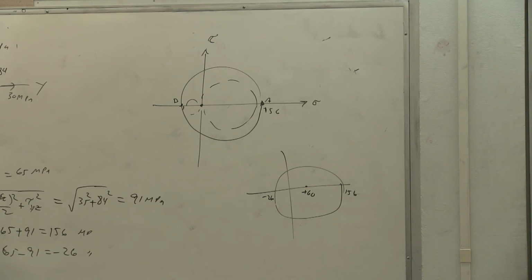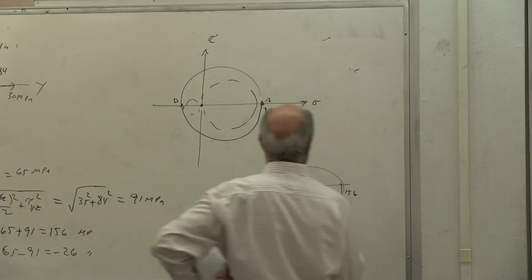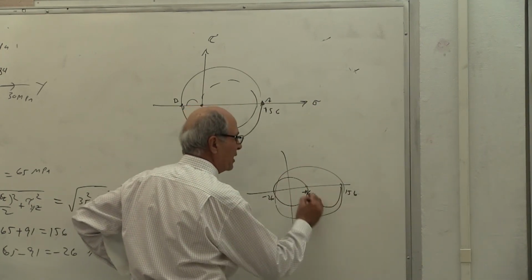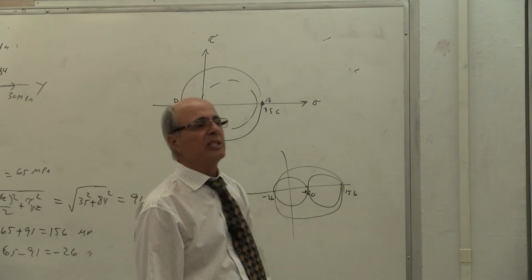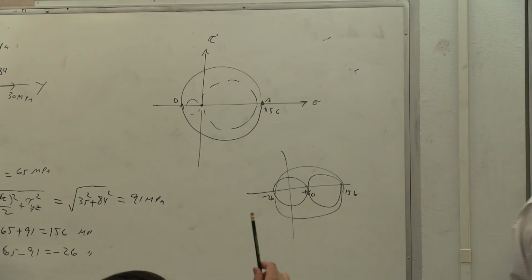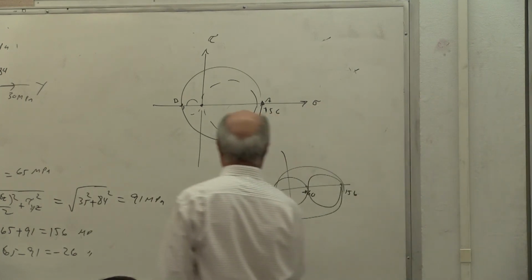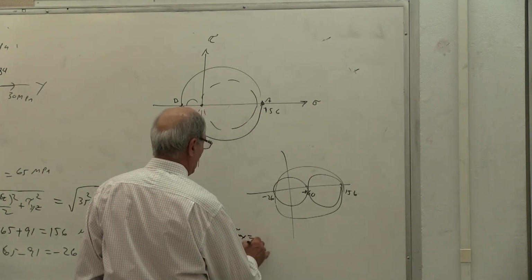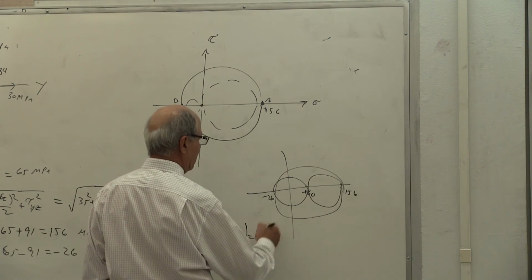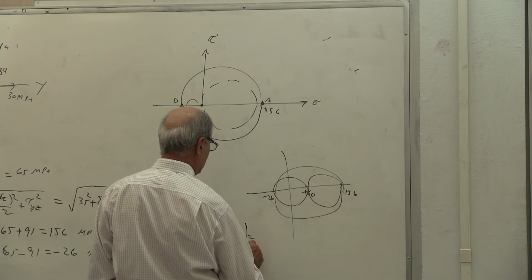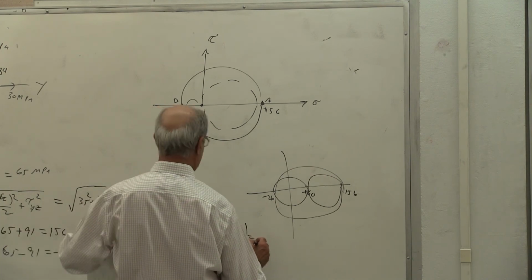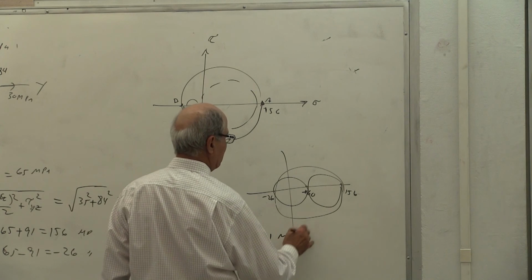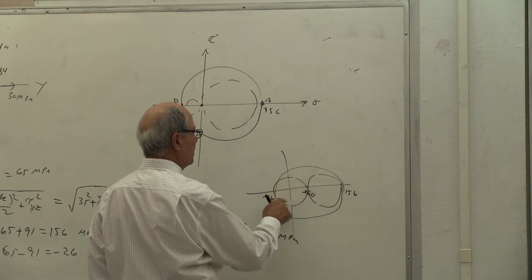Yes? Now, therefore, it is 60, and then the other two circles become like that. Is that correct? Which become again insignificant, so the original circle still is the maximum shear. Yes or no? So the tau max is out of plane, original. No, in plane, I'm sorry, because the other two are out of it. So it's in plane, and the same value we got before, which was how much? 91 megapascal in plane, because these two are, usually we draw this in the, correct?